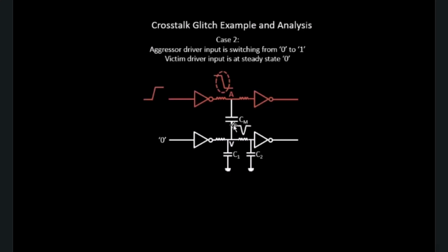It's called a fall glitch because it's at logic 1 and it's falling to some other potential which is less than logic 1, hence it's called a fall glitch. Let's talk about that in some time, but this is what is happening in this scenario. The scenario is exactly the same as before, it's just that the bucket is now placed in reverse, and whatever water was filled in this bucket is now getting leaked through this particular capacitor, through this particular bucket, and through this particular inverter. They are getting momentarily discharged, and then again it comes back to the original potential, which is logic 1.